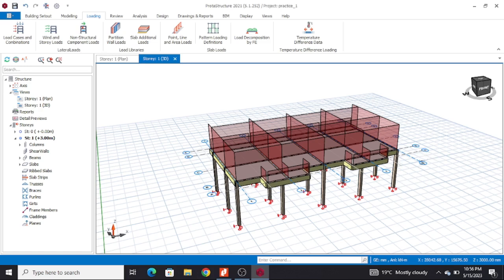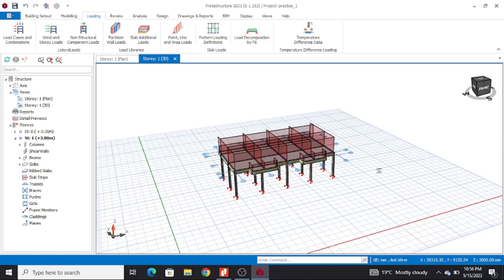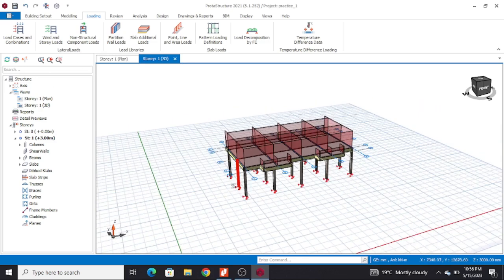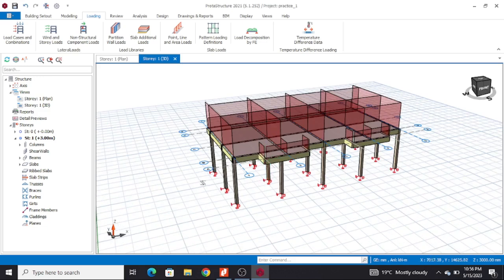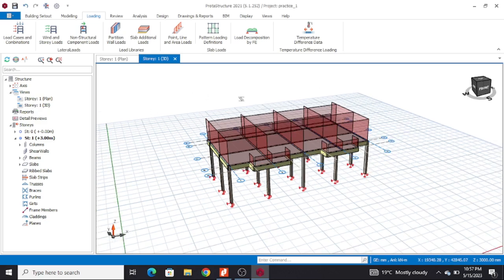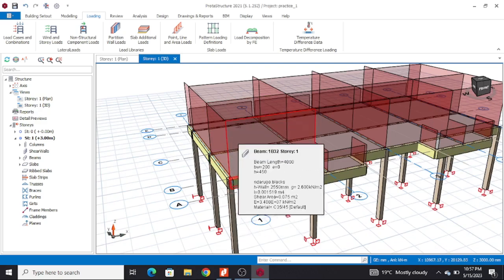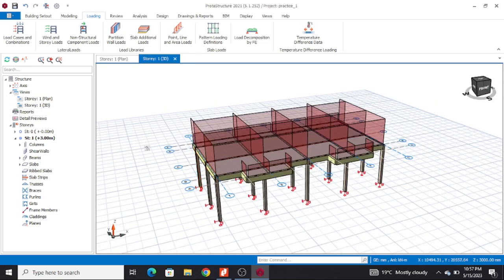After doing this, the next thing is to set my story height, come up with the whole model the way it's supposed to appear. But hope you remember, once I model a floor, it gives me columns carrying beams, and those beams carrying slabs, and those beams are loaded with walls. So if I model the next floor, the columns are going to come to these walls that are existing here, and then the slabs are going to come on top of these walls. I'm going to show you.